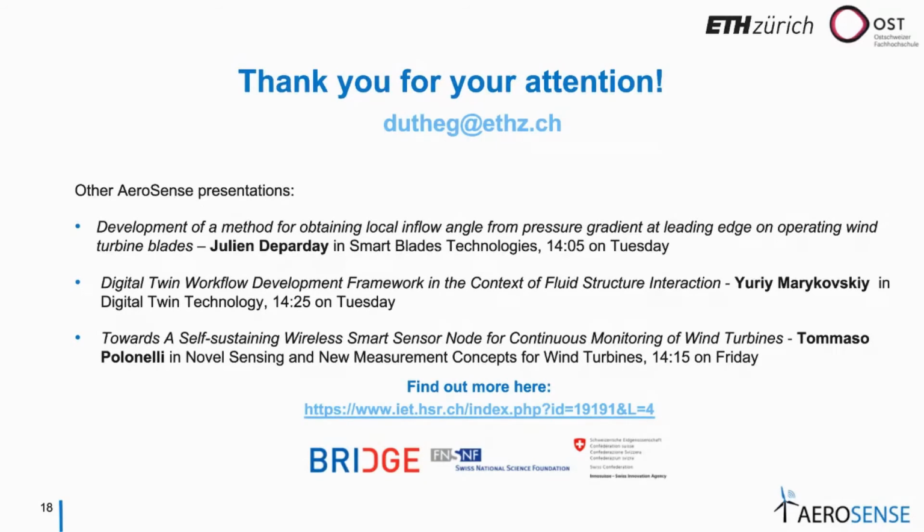Okay, thank you, Gregory. There's a question that came over: thank you for the presentation, how did you implement the roughness of the surface in the OpenFOAM model? What kind of module did you use in it? So that's a good question. We haven't modeled the roughness in a physical way. We're modifying the wall functions actually. So it's just the equivalent sand-grain roughness of the wall functions.